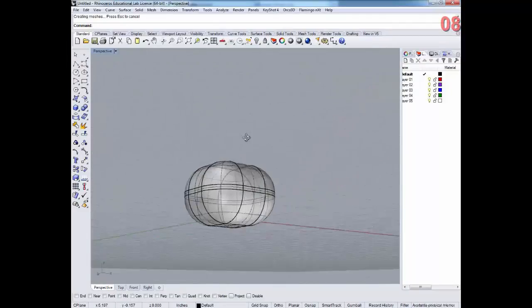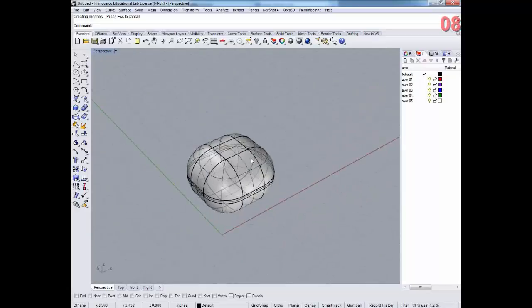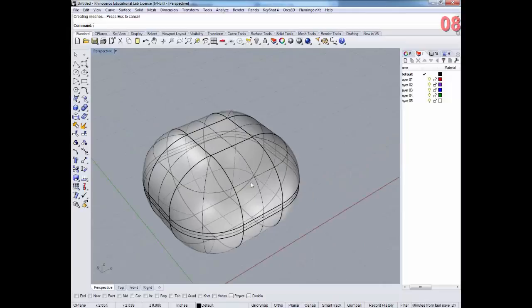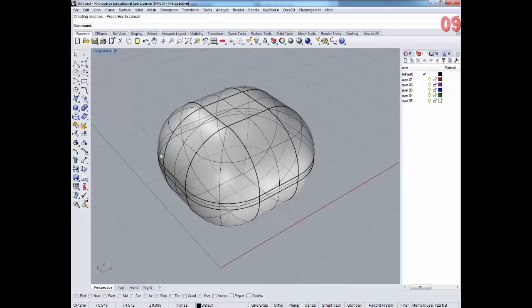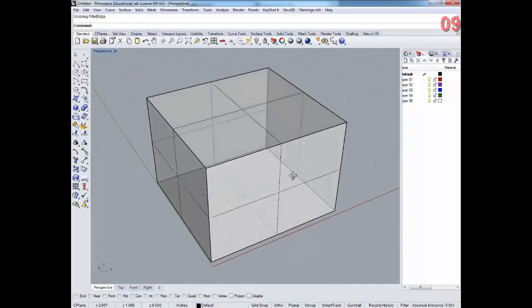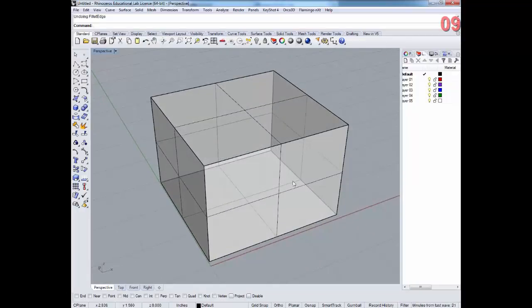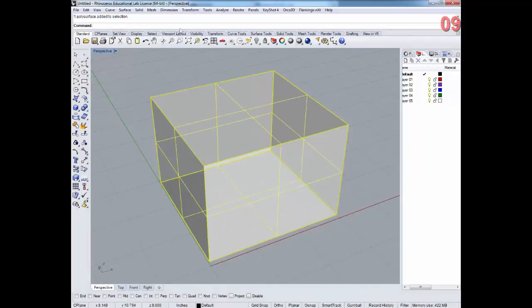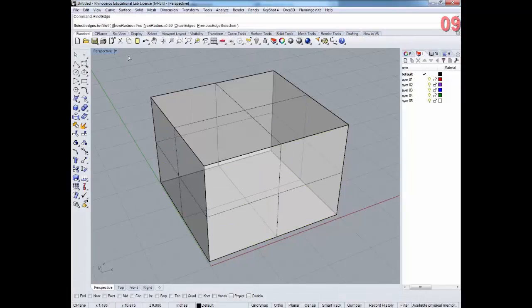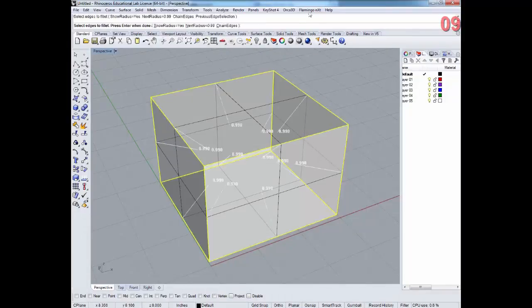Okay. So up until now we've been applying 1 and 2 values to our fillets. We can also customize our fillets to give our shape a unique shape. And one of the reasons why I'm starting out with a simple rectilinear primitive is that I want you to see the potential of filleting. So let's go again. Let's select this object and let's go get our fillet edge command. I'm going to select all of the edges to fillet, and I'm going to press enter.